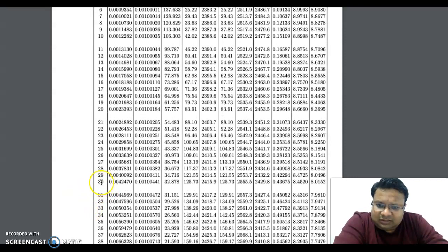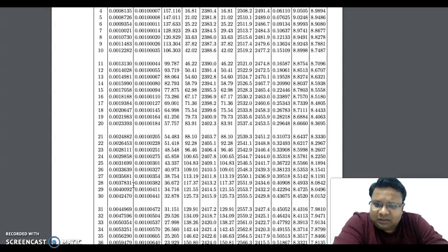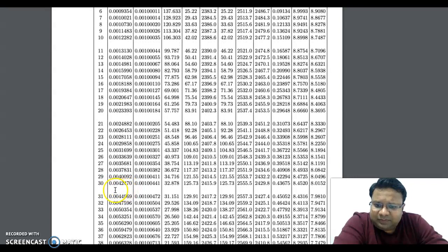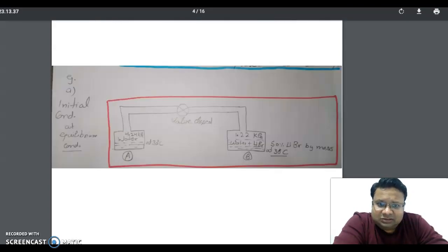Likewise, if in reservoir A we have the temperature as 30 degrees, then across that 30 degrees we have a saturation pressure of 0.00424 megapascal, or we may call it 4.24 kilopascal. It is in megapascal, multiply with 1000, it becomes 4.24 kilopascal at 30 degrees Celsius. So the water is at a pressure of 4.24 kilopascal at this saturation temperature.